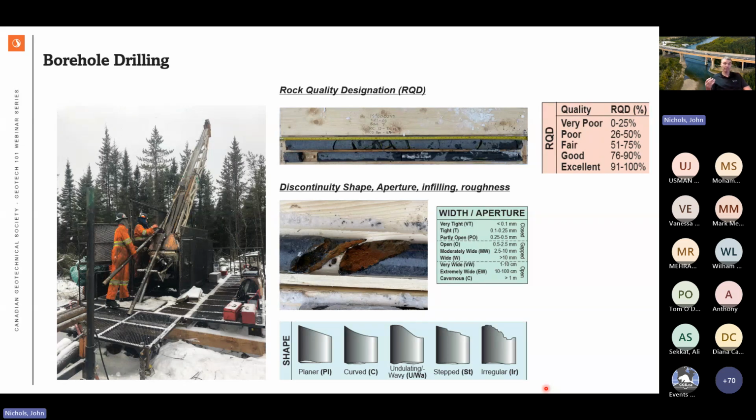And with drilling too, if you don't have any exposed faces for your excavation, you will get some rock quality. You will find out some fracture zones. And even if you can correlate a fractured zone at the surface of an excavation, drilling behind a rock slope will allow you to correlate and maybe give you some more information on whether it narrows out or extends, all good stuff. And again, we'll still get roughness data and shape data from borehole data.